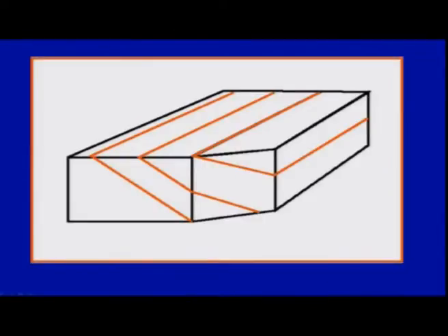and understand which phase you are looking at, because that will depend on whether you are measuring the true dip or the apparent dip. Okay, that is extremely important. So here is an example which shows, if you are measuring exactly perpendicular to the direction of the strike, because this will be your strike here, that will give you the true dip.